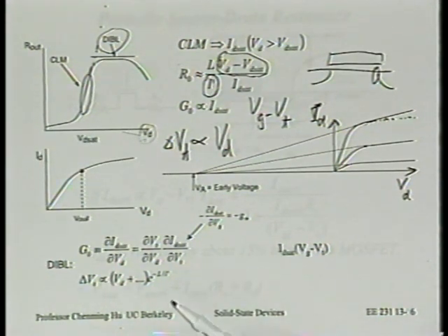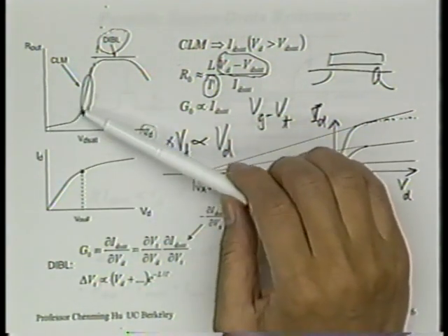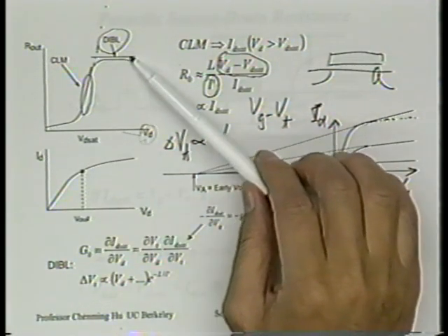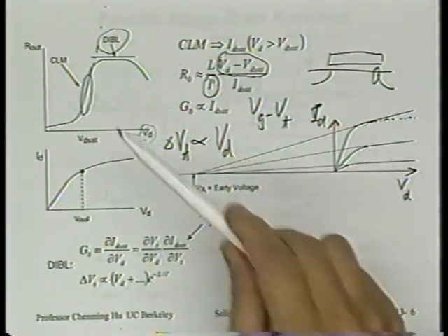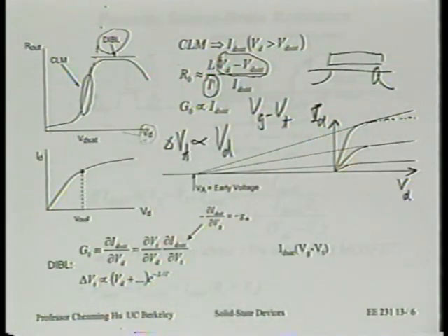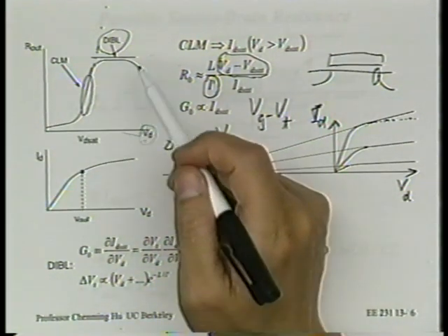So to me, it's a very reasonable assignment. This part is channel length modulation. This part is DIBL. Okay? And then later we'll talk about what is responsible for this part. But most of the transistors we use today, at least up to 0.18 micron, at least if you get it from TSMC, for example, because it's a general purpose transistor, you really don't see this part.